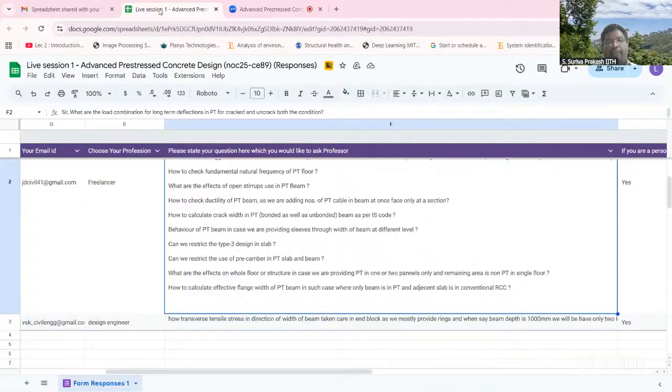So that affects most of it, because what happens, as you said correctly, you are a consultant, somebody gives you the PT vendor, does all the calculations, and then you put in your drawing and then submit it, right? But what is the effect of this, particularly depending upon your structural support and the stiffness of the supporting element, then you will develop additional moments. So that you have to take into account. That typically people don't consider it.